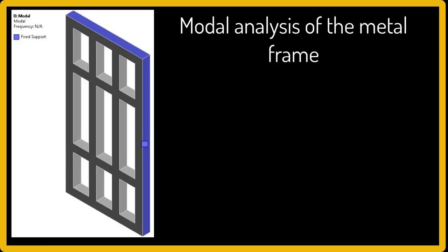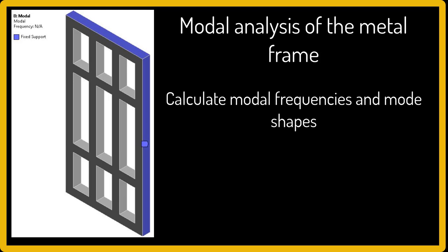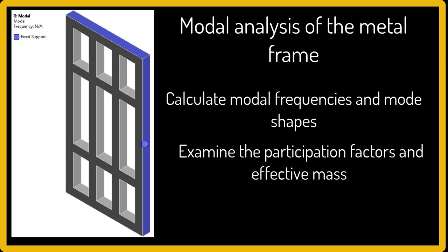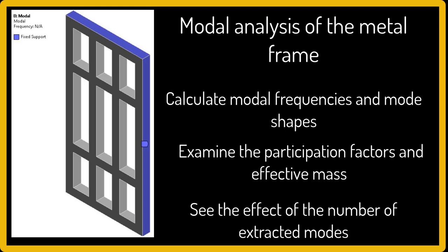Let's go and see how we can do modal analysis in Ansys Mechanical. In this demo, we will show you modal analysis of the metal frame and how to get modal frequencies and mode shapes. Additionally, we will look at the participation factor and effective mass and see the effect of number of extracted modes on these quantities.